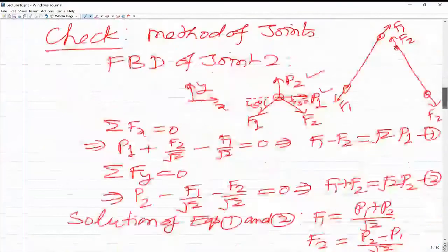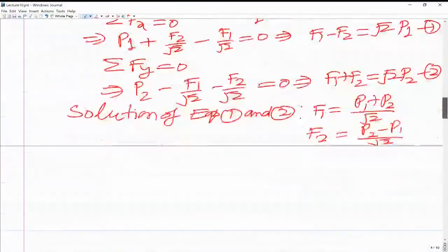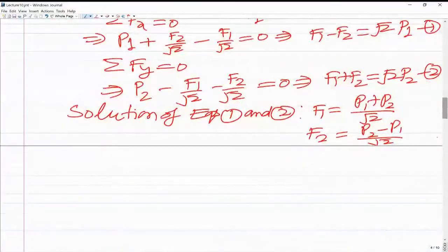So now you see that for this case the finite element is giving us the exact solution that we get from the method of joints, because the forces are acting only at the nodes, so there are no distributed forces. In that case the displacement within each element will be linear in capital X, and that is what we have already assumed in the approximate solution in FE. So FE gives you the exact result for this particular case.